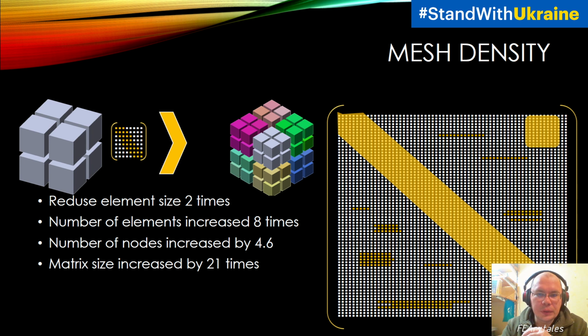So Autodesk Inventor, Nastran, and many others also will use linear and nonlinear or quadratic tetra elements and only tetra elements. Some of the big software like MSC Patran, like Siemens FEMAP, like ANSYS can use very different types of elements.